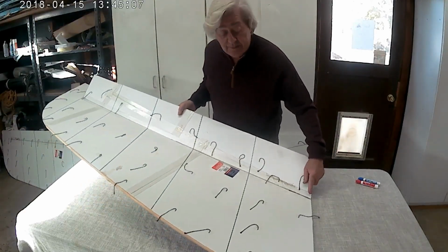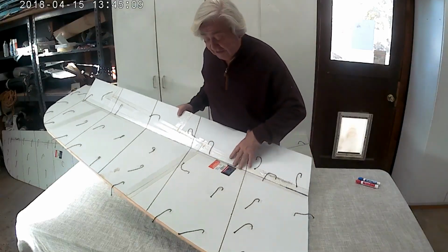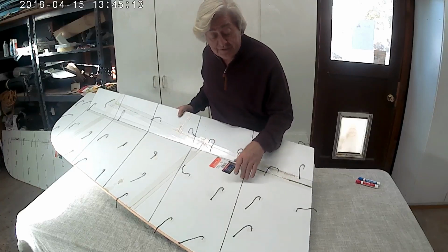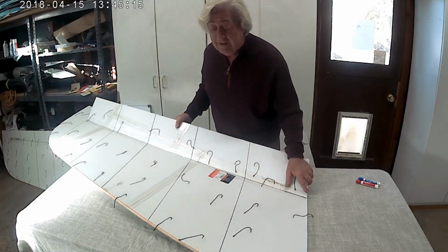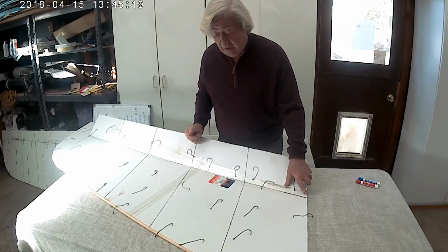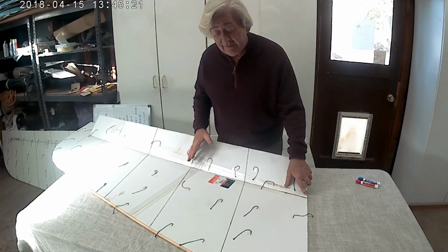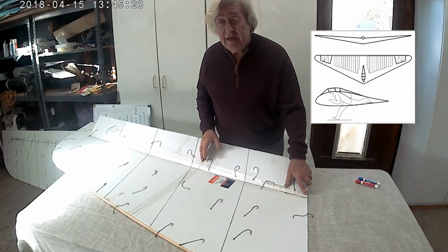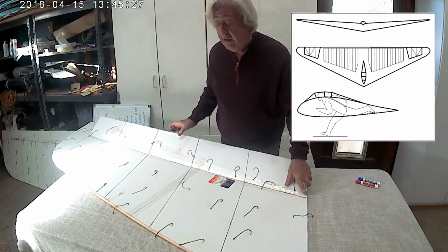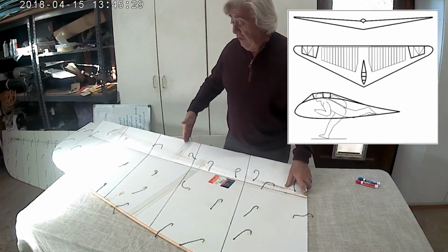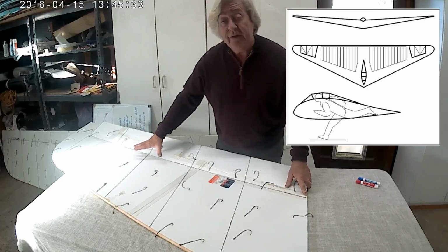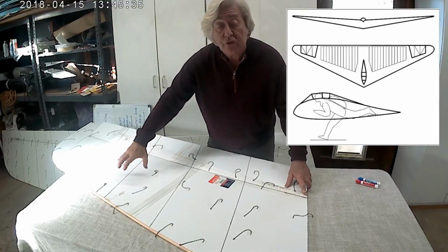Here we have an example of that. A barn door elevon is generally a large percentage of chord, somewhere around 25%, 30% of chord, sometimes even more. The Horton brothers were working on elevon shape also, and I'll put up a picture here of their foot launch version in Argentina, where you'll see that their barn door elevon goes way up like this, up to the spar and back, and it's got a very short span on it, but a huge chord.